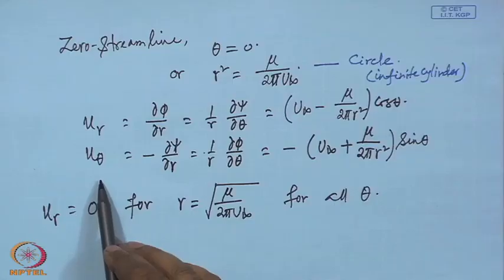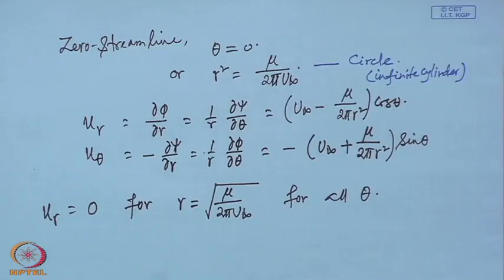So, this is now flow past an infinite circular cylinder. The velocity field on the surface of the cylinder, now we will call it the cylinder. So, the velocity on the surface of the cylinder, the radial component is 0 and u theta is of course now the tangential component. The tangential component is given by this. You can substitute now what is r.